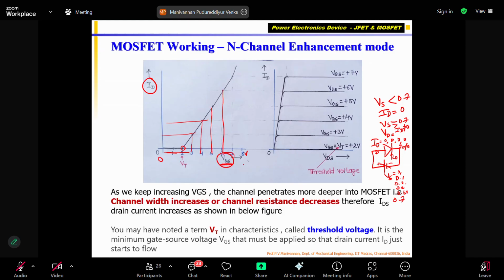So this is the input control voltage. This is the output, correct? Drain voltage. You can say this is 1 amp, 2 amps, 3 amps, for example 4 amps, this is 5 amps, correct? But up to 2 volts, even if I vary the gate voltage, the control voltage, the output current is 0. You can see the current remains 0, right? Vertically it is not moving.